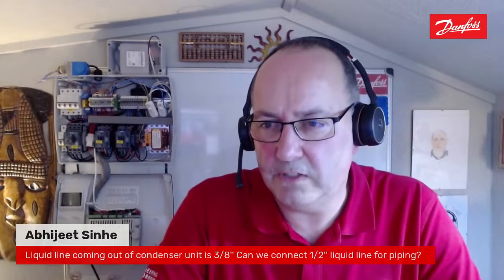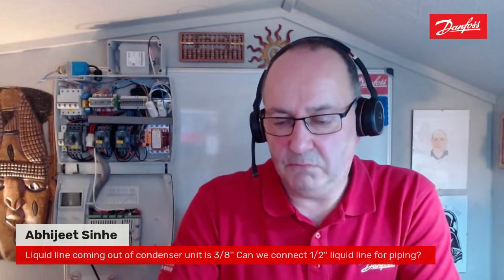Okay, there we've got another question coming in. Liquid line coming out of condenser unit is 3/8. Can we connect 1/2-inch liquid line for piping? Yes, you can, but this comes down to making sure that you've got the correct velocity in your pipes.